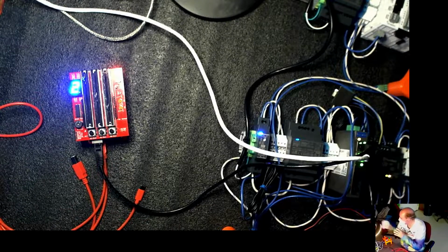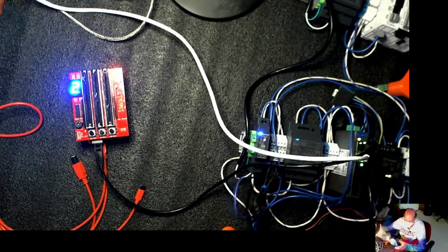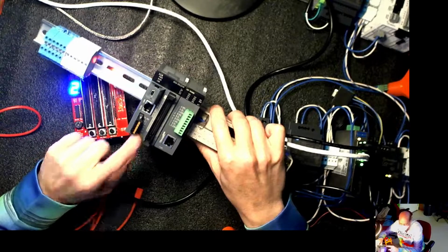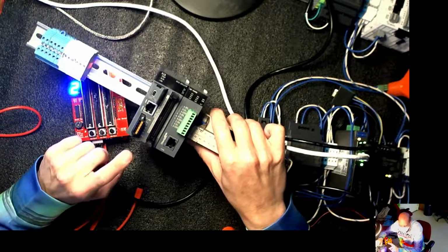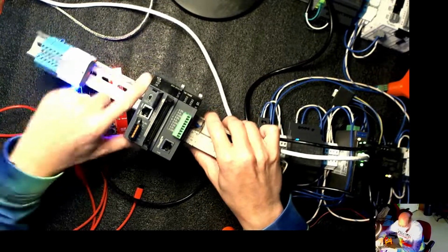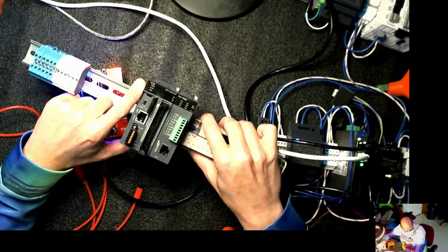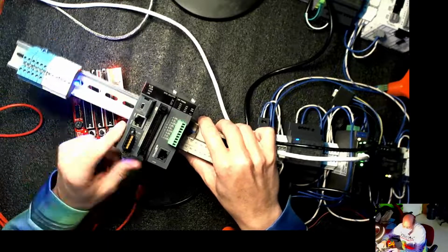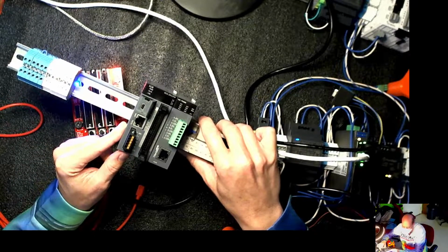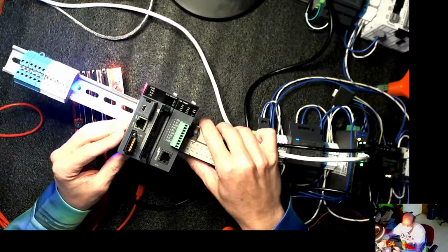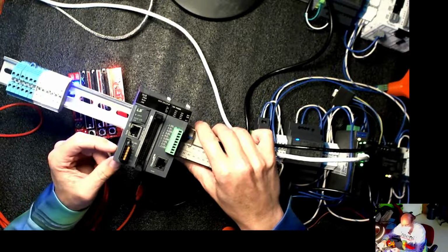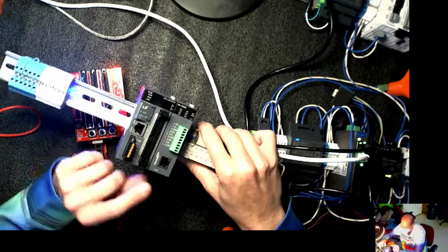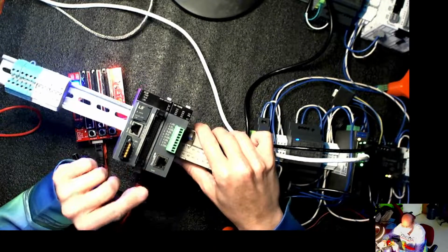And then this is another PLC I bought for work. This module here, the CPU, is about $400, and you can program it in structured text or ladder or the other languages. Sorry, this is from LS Electric on Automation Direct. It's called the XGB. A reason you might play with it without potentially buying one is you can download the free software, and they have a simulator in the software that you can run on your PC. The reason I purchased this one is because the CPU has 6 axes of step and direction, and then for $400 you can buy an EtherCAT master for doing motion control.